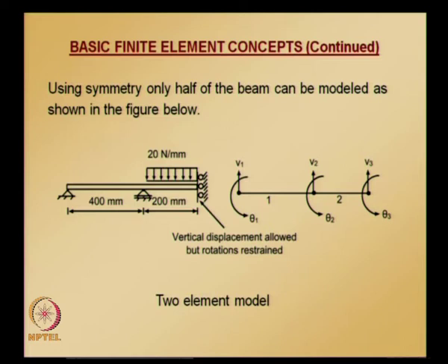So, we will take the stiffness matrices from the previous calculations and concentrate only on the load vector for each element and assemble the global load vector.